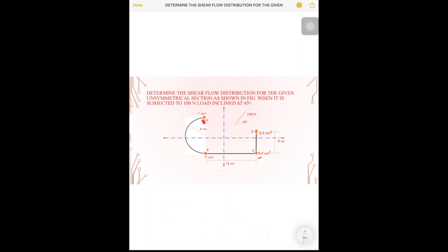So we have taken the reference plane AB. So our neutral axis is 5.33 centimeter away from our reference point. The same way for y, we have taken the reference plane as BC and our neutral axis is 5.33 away from our reference point BC. So this is our neutral axis.